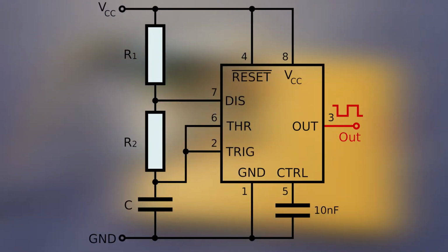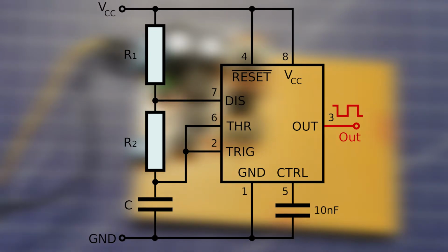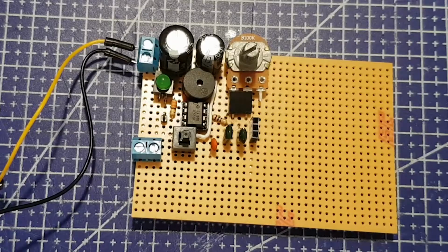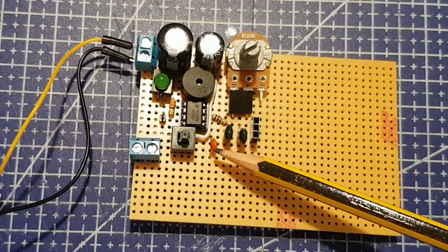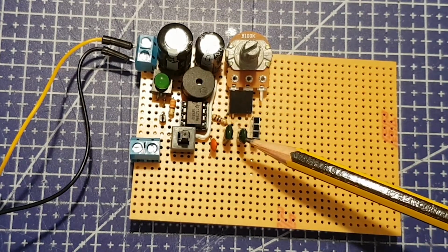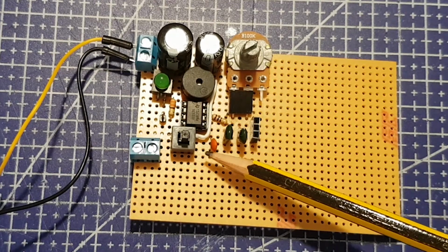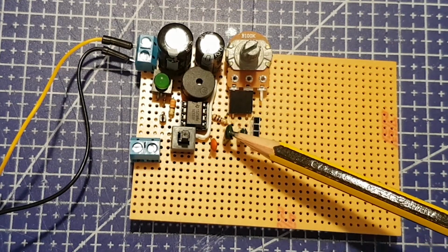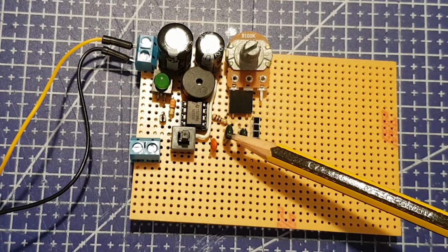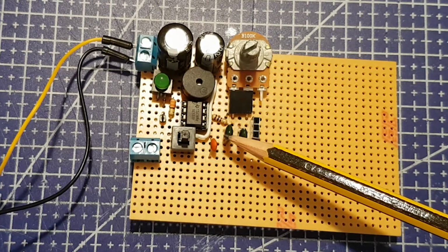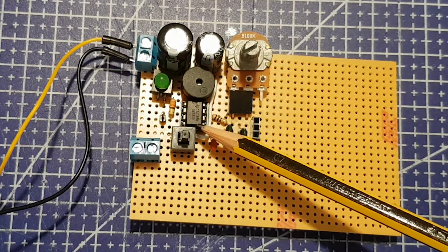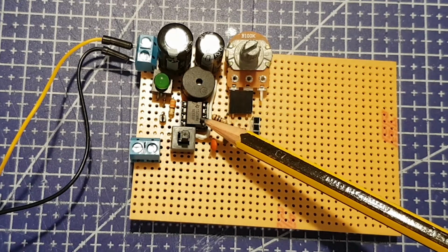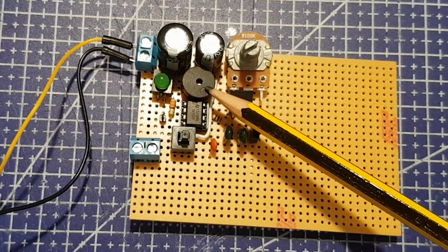And they are also used quite a lot in timing circuits. You might recognise this as a 555 timer circuit. You actually use capacitors on this to adjust the timing of the circuit, because the size of the capacitor determines how quickly they charge up and discharge, and that information can then be used by, in this case, the 555 timer chip to give a set oscillation or timing. This particular 555 timer circuit has a speaker, so you can audibly hear the change in frequency from changing the capacitors.